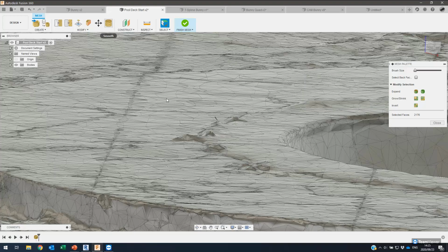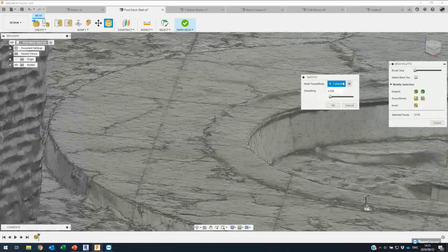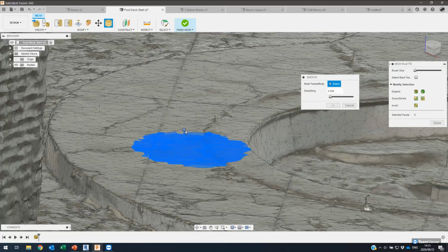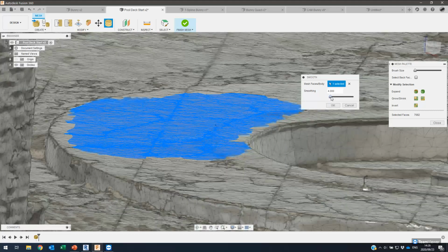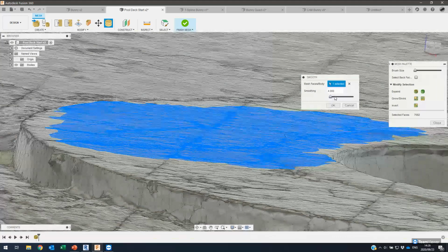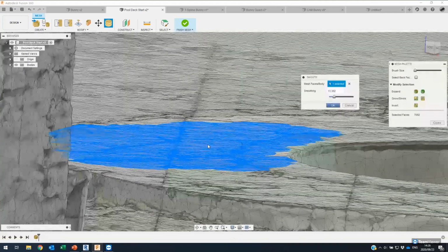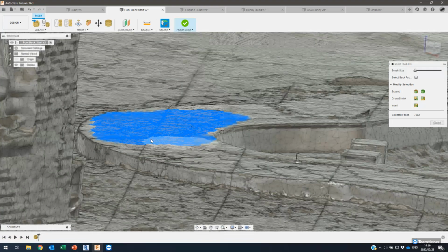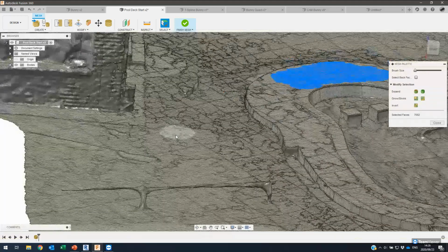and going ahead and picking a portion of the mesh. So I'm going to go ahead and grab some of that mesh around the pool, and we'll smooth off that pool surround. Once again, you also have a weight here, so you can weight how aggressive that smoothing is. The higher the number, essentially the flatter you will get in that smoothing. And that can smooth any unwanted bumps out. If I had to go and smooth out a portion of the grass, we would see the same effects.